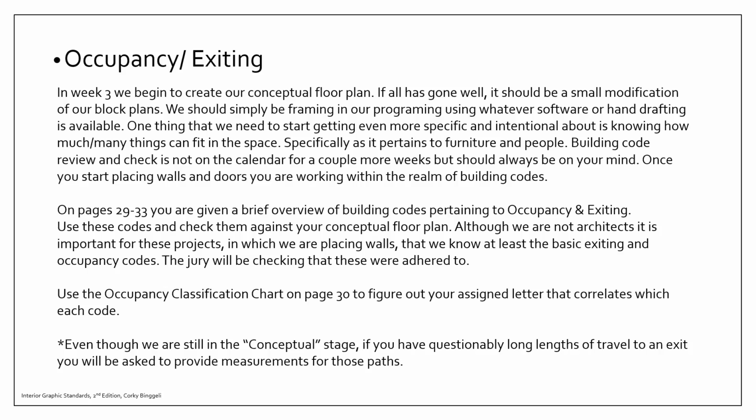So where I saw that being an issue in your project is if you define that space that you're passing from the lounge area on the second floor through a storage area into your cigar lounge. That wouldn't be allowed if you actually qualify it as being a storage area.